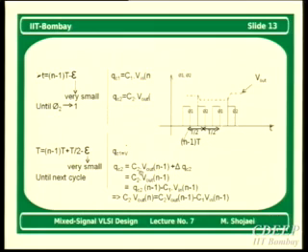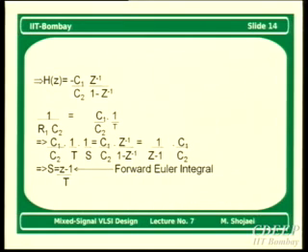So that's why we have this Vout n minus 1 as the initial state already there, and then now we will have a delta Q. It's very simple, and this delta Q is the same as the charge which was stored on C1. Therefore, you just replace it by C1 Vin n minus 1, and then you will get a simple relation for this integrator. And finally, you will get a transfer function of the integrator, which will be forward Euler.